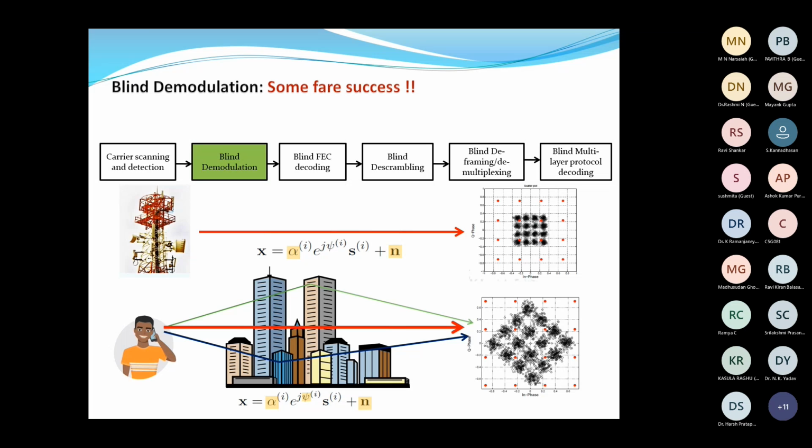The second scenario is a static target encountering multipath fading due to reflections from buildings, vegetation, military vehicles and so on. In this case, with the observation interval being fairly static, we have the amplitude uncertainty and the phase offset under Gaussian noise, and we have fairly well resolved this. The first scenario being a subset of the second, we can say it is well resolved within these two scenarios.